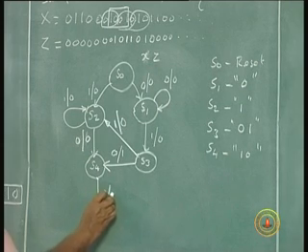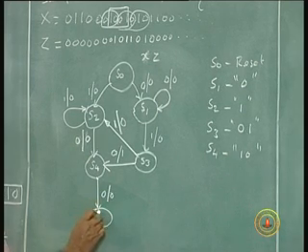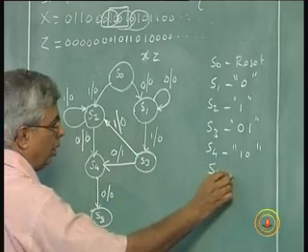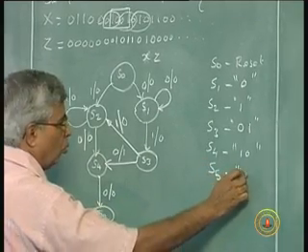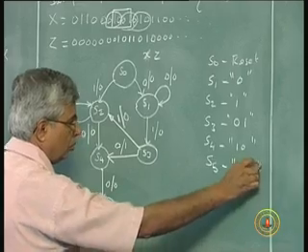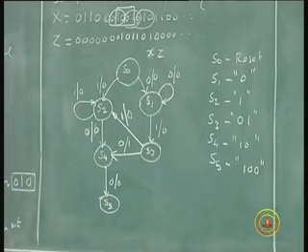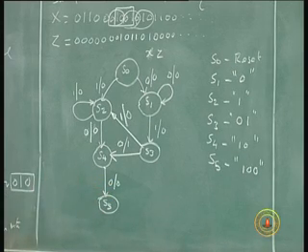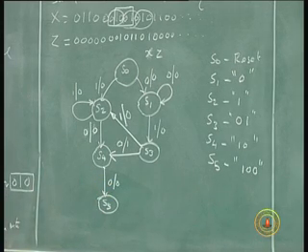We will go to a new state called S5, which will remember 1 0 0. No output again, because only when 1 0 0 1 is completed we will have an output of 1.